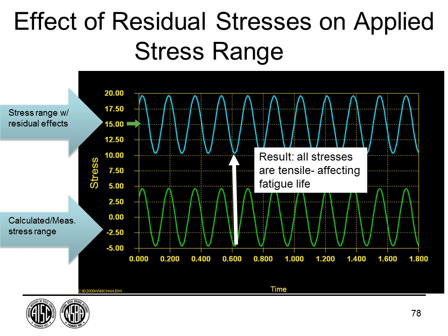That's the locked-in stress effect, right? So instead of cycling 5 to minus 5, I'm cycling 20 to plus 10. So I have a full stress range. In other words, the entire stress range cycle is what keeps the fatigue crack growing. And that's explicitly included in the AASHTO specifications, where we require you to check and include a portion of, or the compression portion of the stress range cycle. It's because of the tensile residual stress effects.